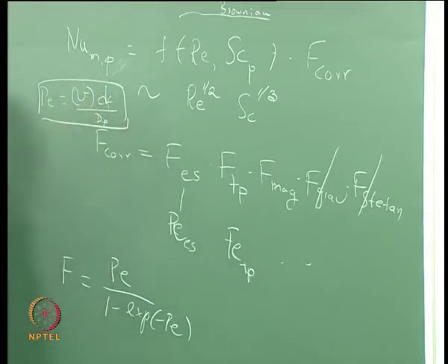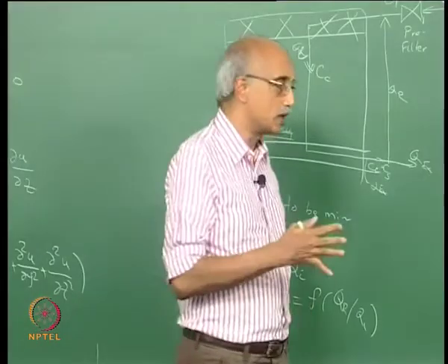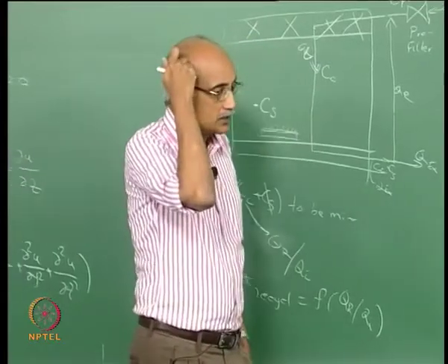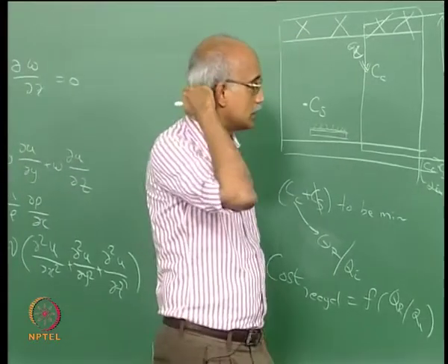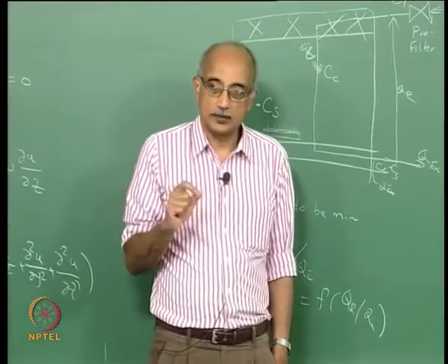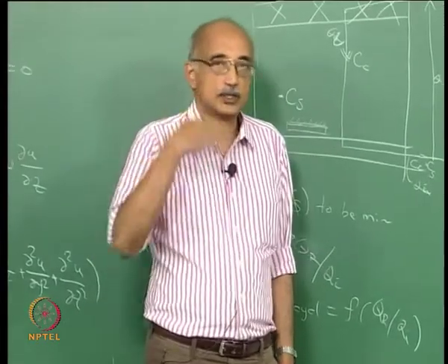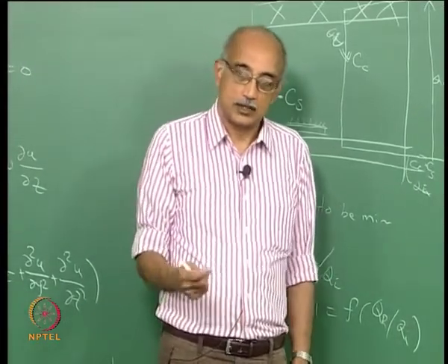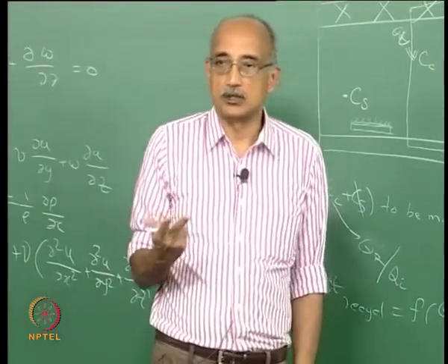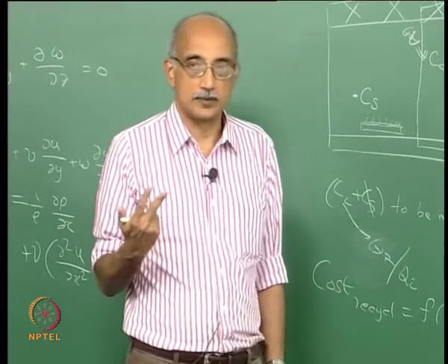So, once you know the Nusselt numbers, you can calculate the associated rate of deposition by multiplying this by the reference quantity for deposition flux. Now, this exercise is important to do because the thing that we need to really work on inside a clean room is, in addition to controlling the particulate levels in the environment, the placement, orientation and time of exposure of product are the three most important variables.